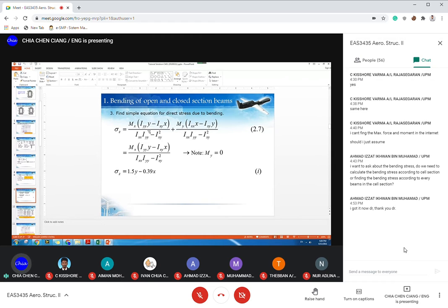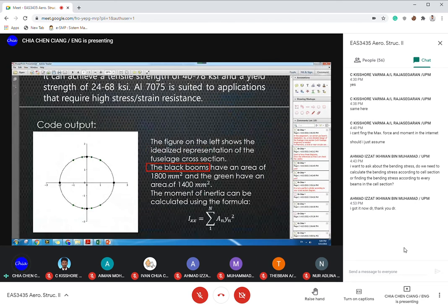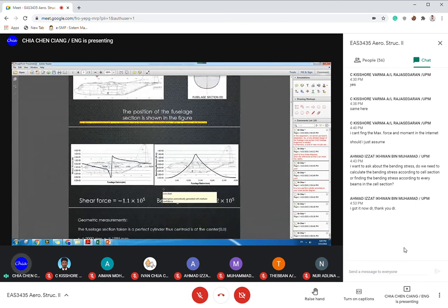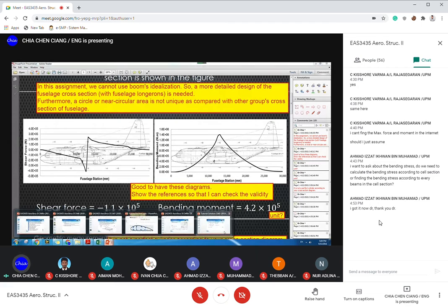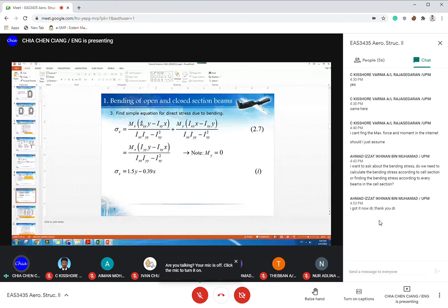Iyy, plug in the value. Ixx, plug in the value. Ixy, plug in the value. Then moment Mx, moment My. You need to get from your analysis, from your aircraft model analysis, what is the value of the bending moment. For example, this particular bending moment is from what direction? Is it Mx or My? Once you identify that, you can plug into the equation.